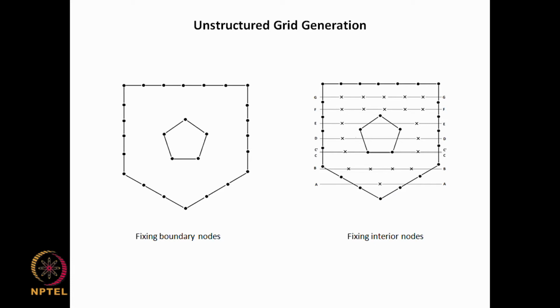Now, along this line I fix as many grid points as I need in order to have a separation distance of about small l. So, for example, here along this line this length is short, maybe I will have just 2 points here, two intervals here.